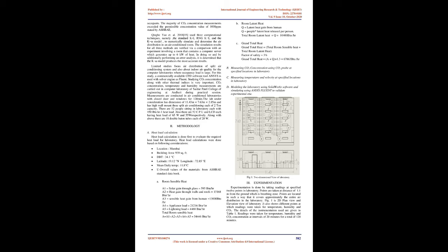Measuring the indoor CO2 concentration is often used as an alternative to determine the indoor air quality. CO2 is a natural air component, and in a given air sample it is commonly expressed in parts per million, ppm. If indoor CO2 levels are more than 1000 ppm, ventilation is probably inadequate, and occupants may commonly complain about headaches, nose and throat ailments, tiredness, lack of concentration, and fatigue.